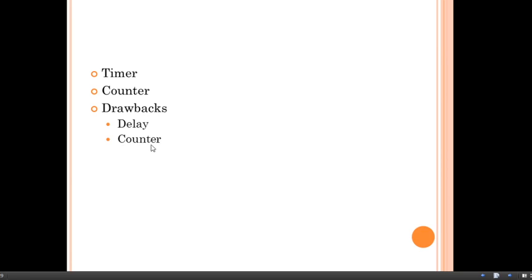Next is related with the counter. 8086 can count number of pulses arriving at the port, and to implement this, 8086 goes on checking the port. If it finds that the port is active, it increments the counter by 1, otherwise it will go on checking the port. Again here the same disadvantage is there, that 8086 will have to execute the instruction and 8086 will remain in busy condition. So in case of larger systems where 8086's time is critical, specific timer ICs are required.